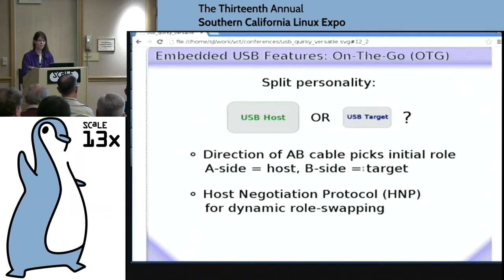Now, this seems like a really cool thing, but technically I haven't actually found a lot of uses for it in the real world. A lot of times you just decide which way to plug your cable in, and that is the direction that you'll be using it for a while. I haven't seen a lot of this. You'll find test pages online that tell you how to do this role swapping. It seems to be kind of board specific though. It's like, well, if you go poke this over in the SysFS area, then you can trigger a role swap. I haven't found any standard ways to do it yet.